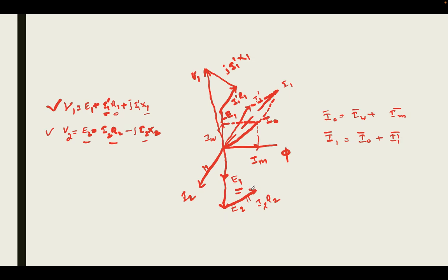Now, drawing another phasor which is at 90 degrees, that is j I2 X2. This angle is 90 degrees. Up to this point, and this meeting point, this vector is now V2. The angle between V2 and I2 is theta 2. Here this angle is theta 2.